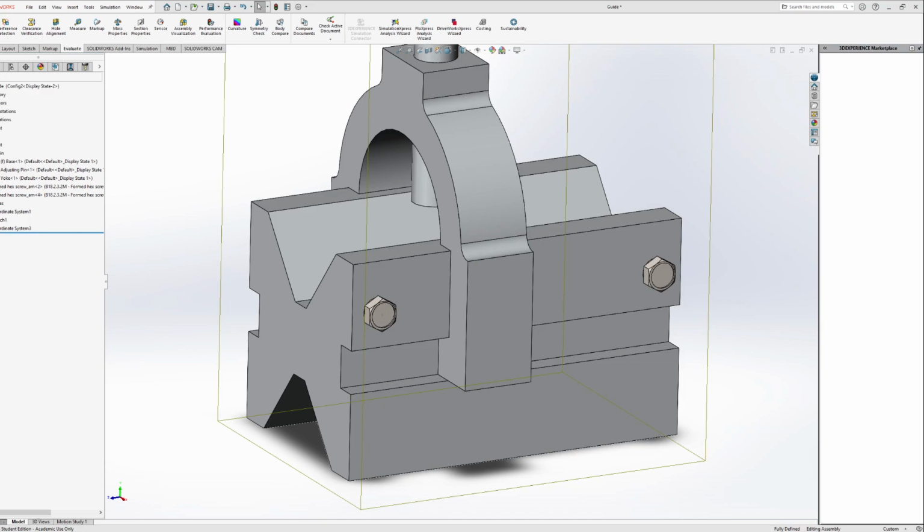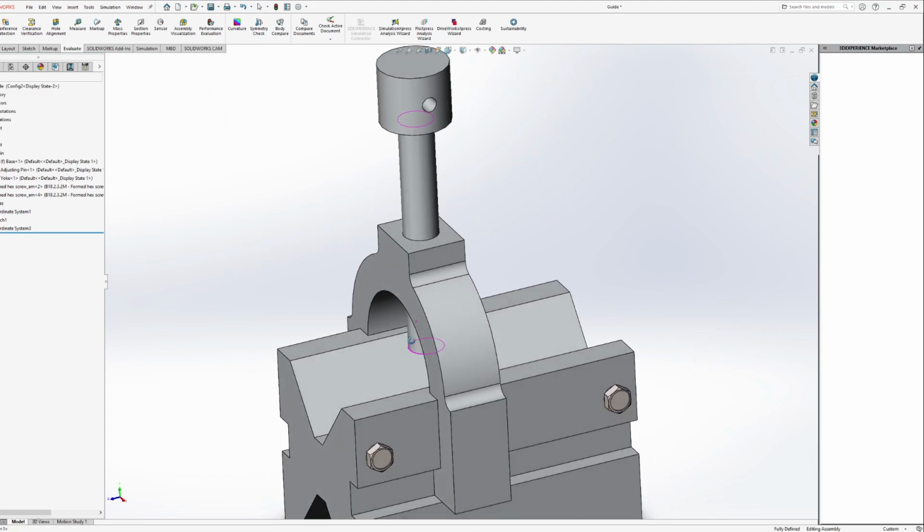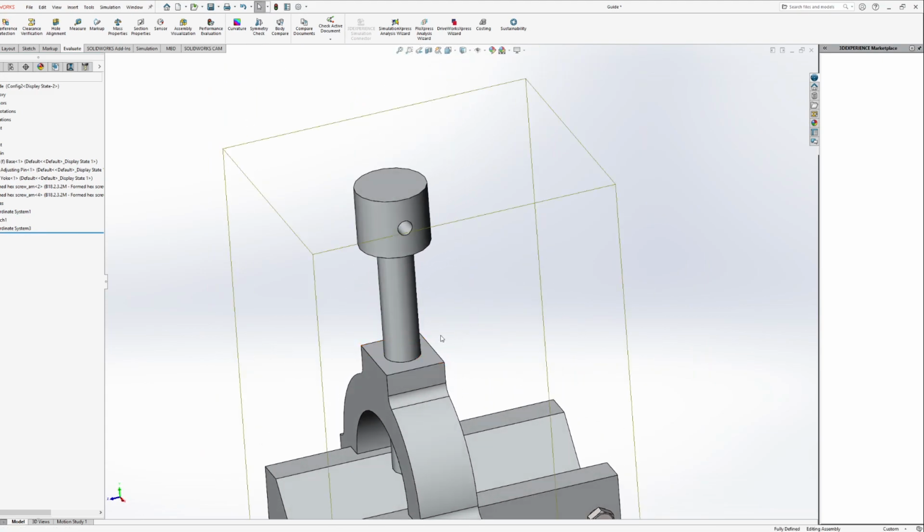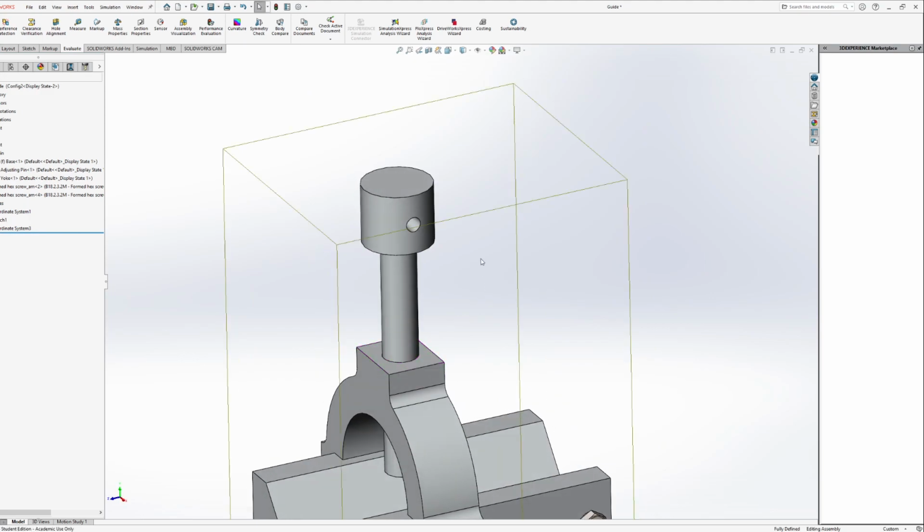I probably should have made a little bit better note of that, or just that you can start sketching in assemblies as well. I wouldn't necessarily recommend doing it frequently, but it is good to keep in mind if you do have instances where you're saying, how could I create a coordinate system there? It doesn't really make sense, or rather, there's no specific vertex that I can select. However, I can create one, and I can create one by creating the geometry required to create a coordinate system, which is just going to be a point or a vertex.